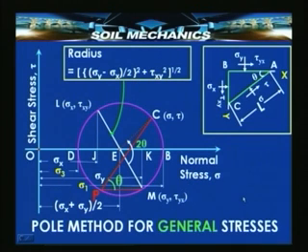We have seen already in detail the step by step construction of the Mohr circle. Therefore, we will not go through that again. All that we need to know is we have a system of general stresses here now, where sigma x, sigma y and tau xy are known. So, we plot sigma x, sigma y, get the points J and K, points L and M, plot the Mohr circle and obtain the point M corresponding to the state of stress on the plane AB.